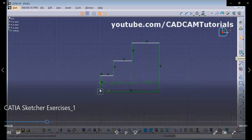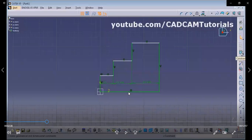Because we specified the total distance from this end to there, and we are also specifying the individual distances from here to there, and there to there. If you specify from here to here also, that means we are specifying individually and the total also. So the sum of these is one dimension, and the total will be another dimension, right? If you have specified more constraints than needed, it will change the color.